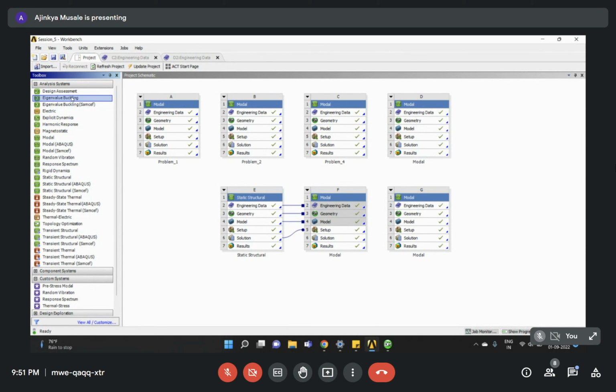This is the main phenomenon of the material which is buckling. Here the input is totally different. For buckling, I showed you the curve yesterday, and it is not exactly similar to my stress strain curve. My stiffness varies according to my load. That's the difference why we have different systems and why we do not just calculate in one system.